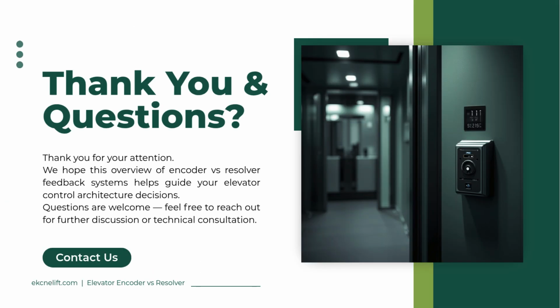For modern passenger elevators, encoders are usually preferred. For harsh industrial environments or some legacy systems, resolvers may still make more sense. The key is not choosing the better component in isolation. The key is choosing the feedback architecture that matches the elevator system, operating environment, modernization plan, and long-term maintenance strategy.